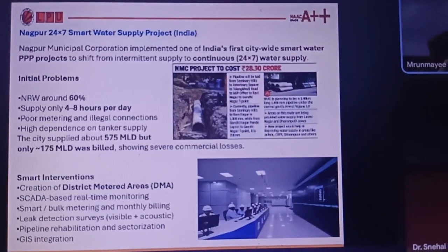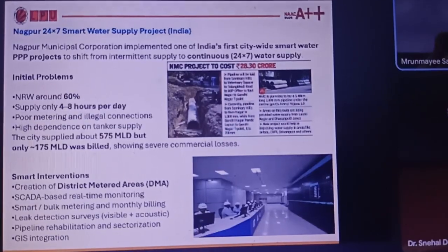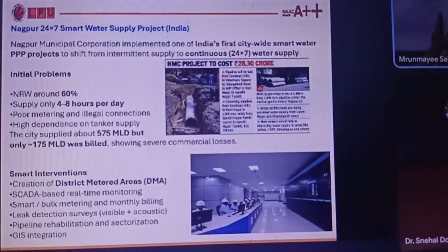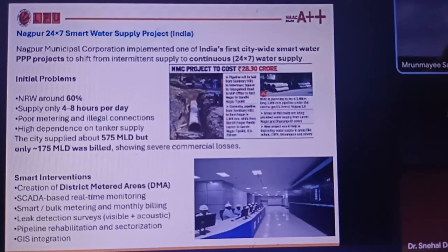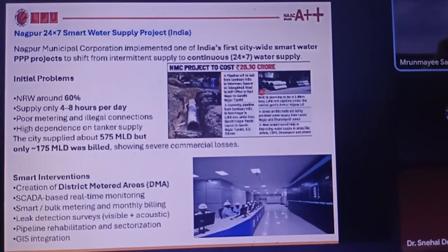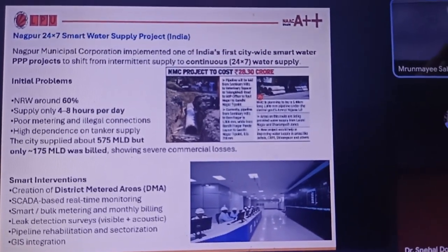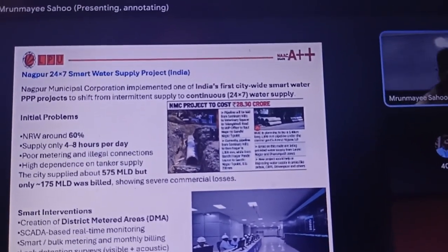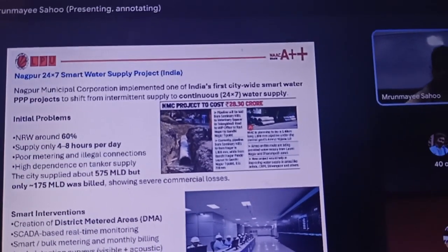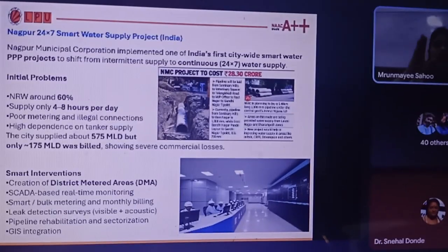You will say, okay, at night time I require 30%, meaning 0.3. From 12 at night up to 3 o'clock we will be supplying 30% of water. Those data again, we have a dashboard where we will take them as multiplier values. And in the morning you say, okay, at night time I have taken 0.3, meaning 30%, so at morning time I'll take 130%. But it should be within the range of the pure amount of water, which is 135 liters per capita per day. If you are taking more than that, that's fine. You can take it, but we are going to charge for it.